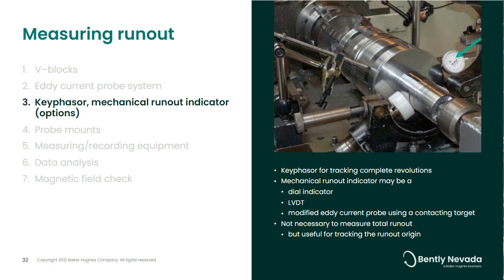So as I mentioned before, if you put a piece of tape around the circumference of the shaft with markings on it, whatever system you use, make sure it's recorded, make sure you've got a frame of reference so that if somebody goes back and they do need to do some sort of reparations on the shaft, they're able to use your same frame of reference and do the repairs where they need to be done.